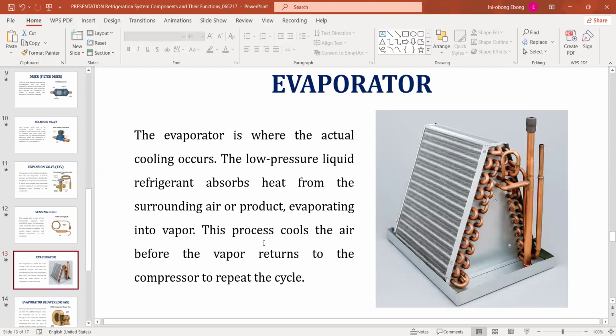And here is your evaporator. The evaporator is where it's going to lose that coolness to the interior of the car, to the interior of your cabin, and further change its state from liquid to gaseous. And of course, the evaporator also cannot achieve that alone, right? You need the evaporator blower. So if your blower fails and is not running, what will happen to the system? It will ice up and return liquid back to your compressor, which your compressor was not designed to compress.